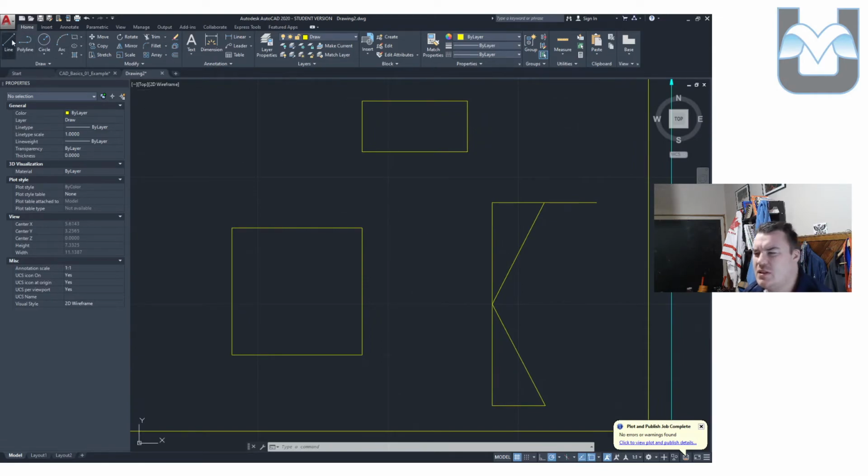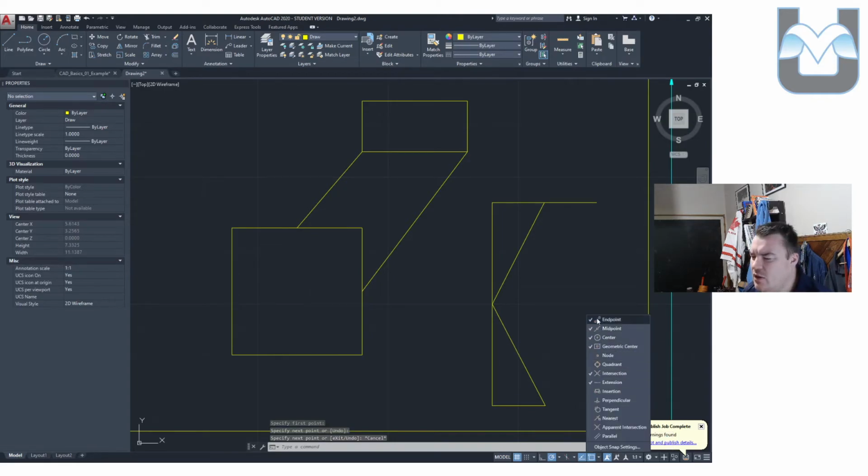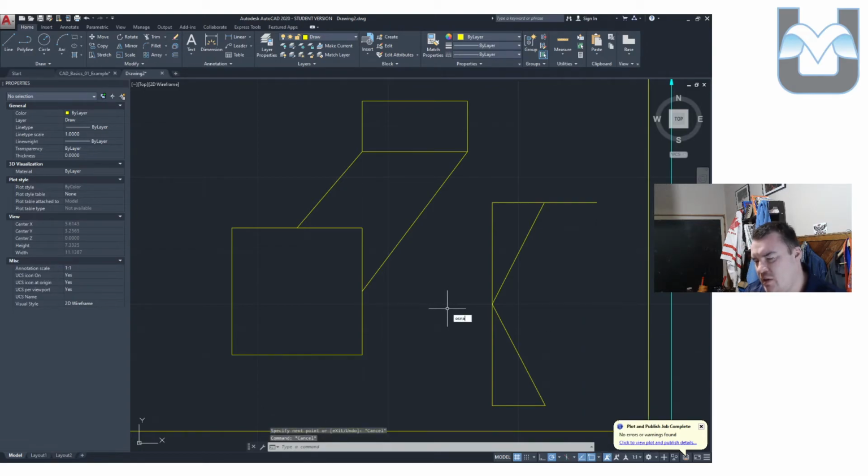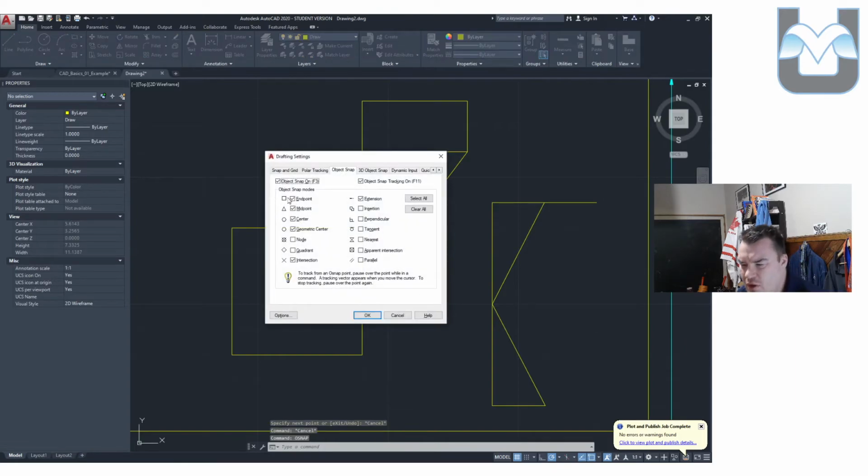Now, the other big snap line that we have to do here is we've actually got this rectangle in the top snapping to the midpoint of things here. You'll notice that the midpoint snap is a small triangle. If you're ever not sure what your snap icons look like, pull open your actual menu down here, and they'll actually start to show up. Oops, sorry, I should say the object snap menu. You can actually see what all of the symbols in your drawing are going to mean as you're snapping to things. So endpoints are squares, midpoints are triangles, etc., etc.